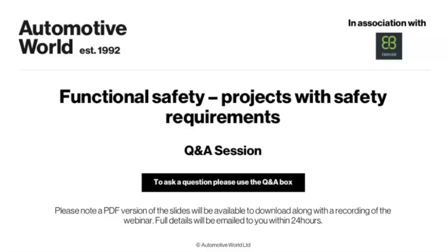No, it does not, right now. It's not able to coexist in the same partition as the ASIL-D software component. At the moment, this is what I mentioned with the ASIL-B ready package. So B like Bravo. But for ASIL-D like Delta, we're working on that, but this is not yet available.